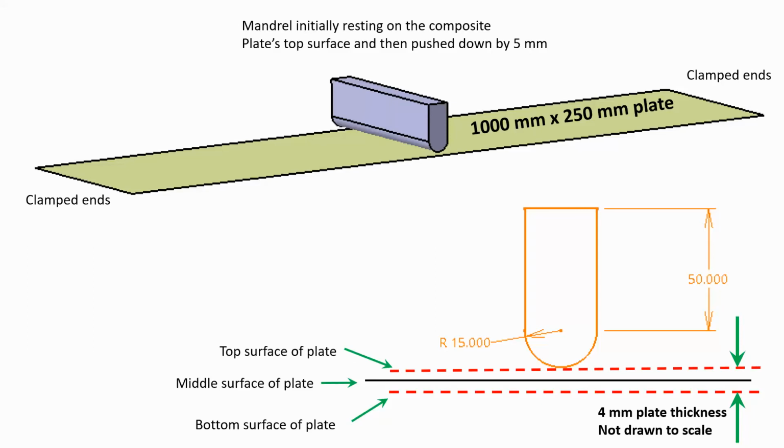Okay, so here's the situation. This is the surface that we're going to model, and then the mandrel is going to be done as a 3D solid object. The properties of it really don't matter because we are assuming that this does not go through much deformation. In fact, many other software allow you to define rigid bodies or analytical surfaces instead of modeling this thing and meshing it with 3D elements, but we don't have that luxury in CATIA.